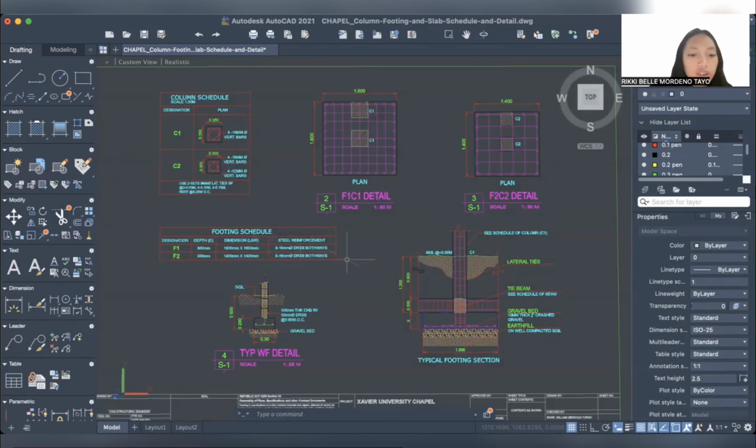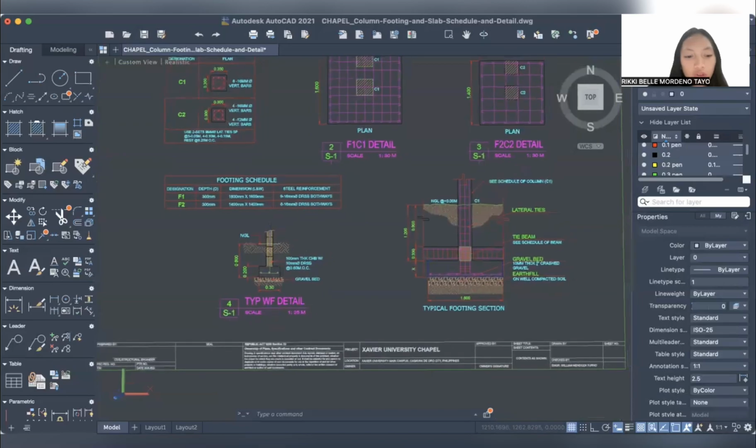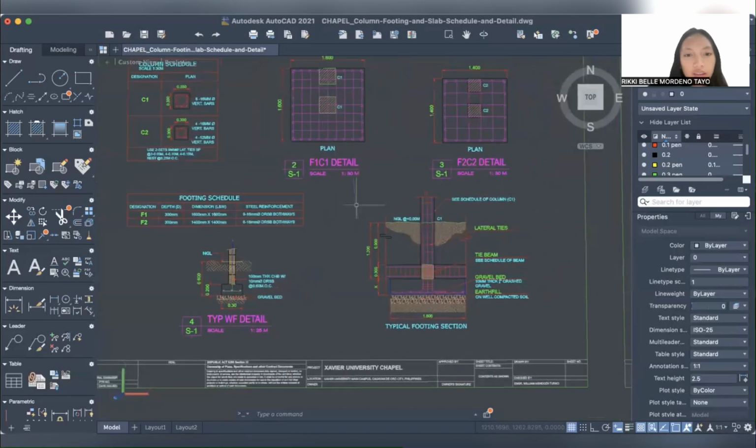The footing includes steel reinforcement to improve its strength and capacity to carry loads. The drawing specifies the type, size, and quantity of the steel bars to be used. Lastly, the footing sits on a 600 millimeter thick gravel bed with 10 millimeter deformed reinforcing steel bars at 0.60 center to center, which helps to distribute the load over a wider area and provide drainage.